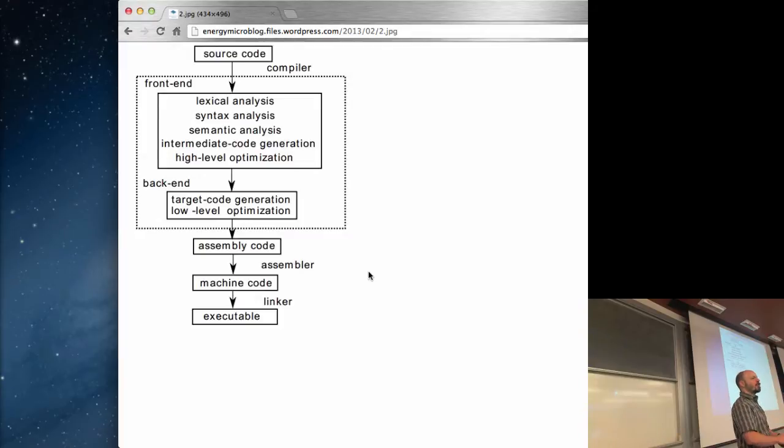For example, we just talked before about how we can wait for 1 second, right? Well, it's very easy. You take a variable, write a number in it, and then just subtract 1, compare to 0, subtract 1, compare to 0, until you have done, for example, 50 million iterations of it, which on a CPU that runs at 100 megahertz, at 2 instructions per cycle, so 50 million cycles would be 1 second.